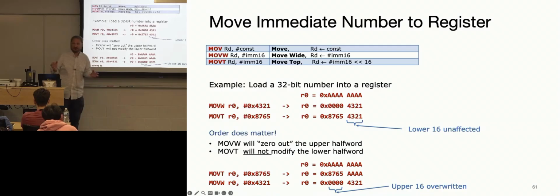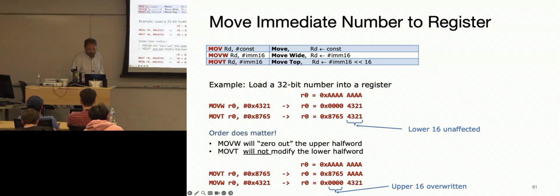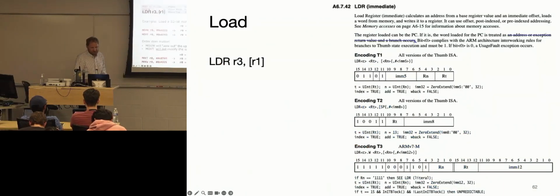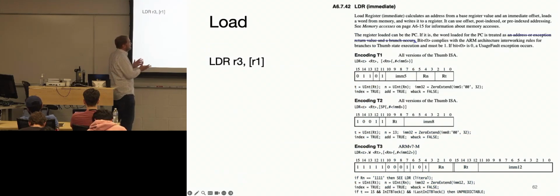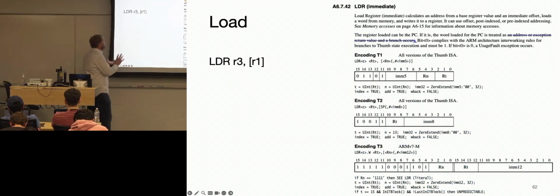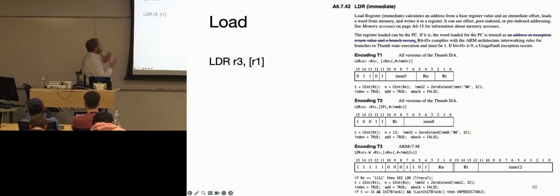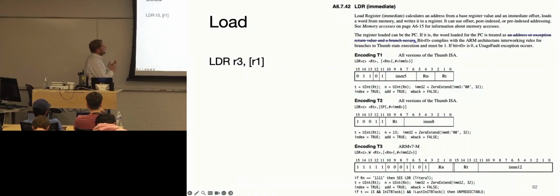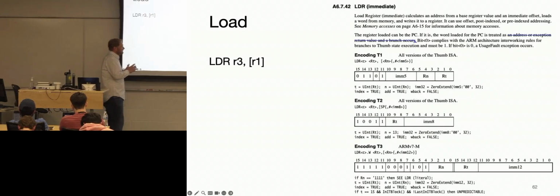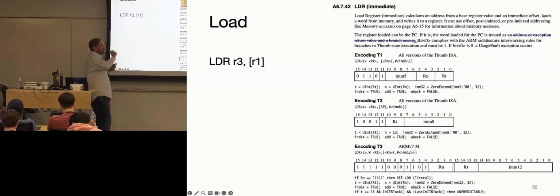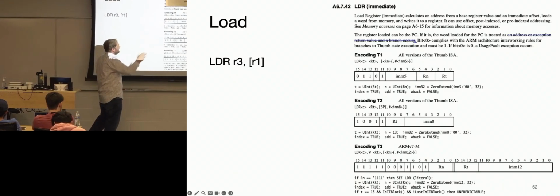What else? Okay. Now we'll get on to things that are specific, you probably haven't seen before, or specific for this particular class. So there's operations like load and store. Load and stores are instructions that allow you to talk to external memory. You're not going to use move. Move is only for manipulating registers inside the core. We're talking about loading and storing data in and out of memory.